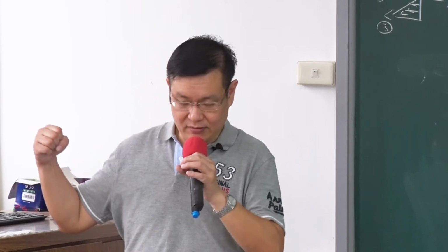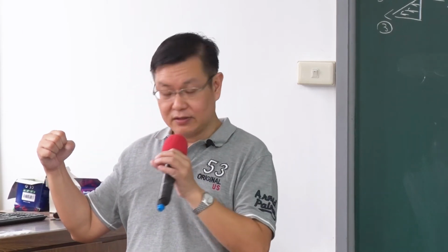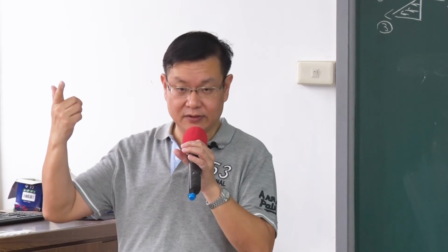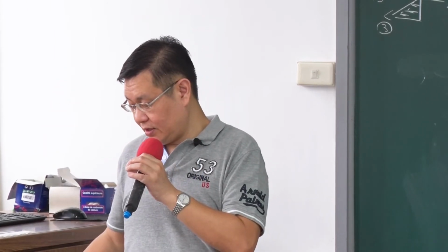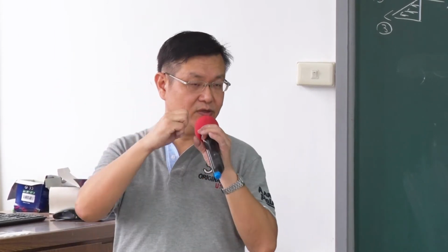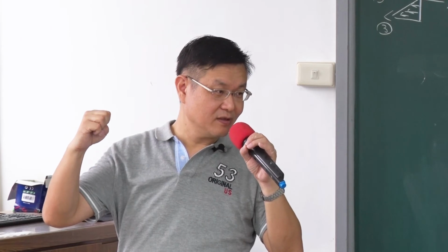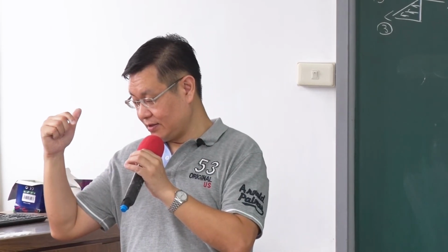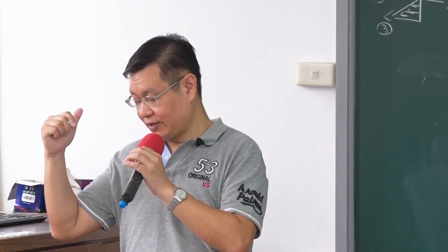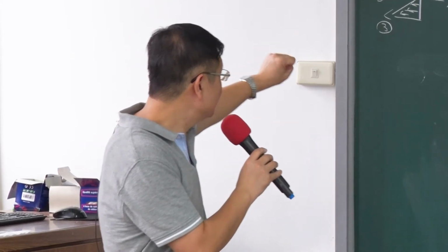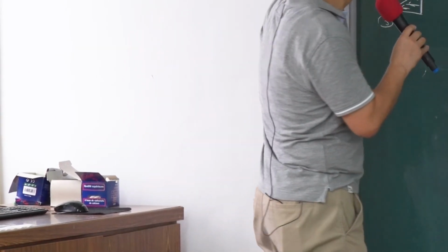When you extend the structure, the rho will increase. And for n-type silicon, when you do extension, the gauge factor is negative, the rho will decrease. It's opposite. Okay.